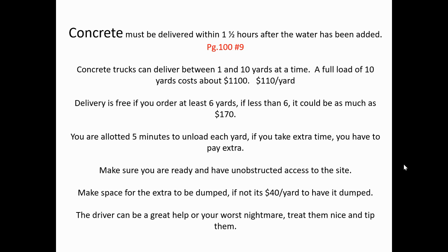If you don't have a full load of like 6 yards, they're going to charge you extra money for just using the truck. And when the truck is at your job site, you get about 5 minutes to unload each yard. So if you had a full load of 10 yards, that's about 50 minutes. If you go over that amount of time, they could actually charge you extra also.